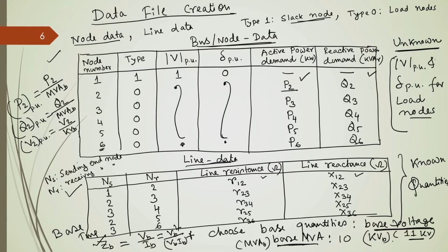Now, we know that here we have the base voltage in kV and volt ampere base in MVA. Now, we can also write it as equal to kVB square divided by MVA B, because if you multiply kVB, kilovolt means 10 to the power 3, two kilovolt quantities effectively will result in 10 to the power 6 in the numerator, and if your denominator is in MVA, this is nothing but the actual quantity multiplied by 10 to the power 6.